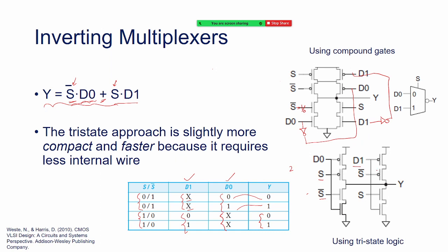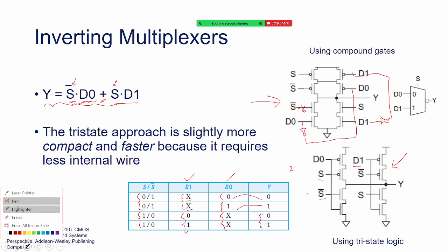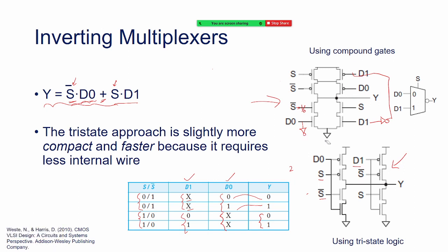Yes. So we'll say that this is a little more compact, and because it is compact it needs less wire, so obviously the delay will be less in the network. So just try to see yourself when you go home, and we'll see how this network can be efficient. So remember this, you only apply the inverting multiplexer by means of this tri-state buffer to create such functions. And the bottom network is restoring logic again. The upper network is non-restoring logic.